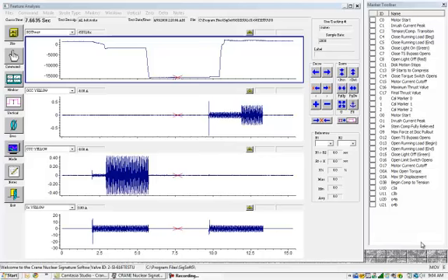The particular trace we're going to do is a globe valve that's got just thrust only because it has an anti-rotation device where the strain gauge is mounted below the anti-rotation device, therefore does not see actuator output torque. To see actuator output torque, you would need to mount a TTC or a VTC on the spring pack, or some other means of measuring torque.